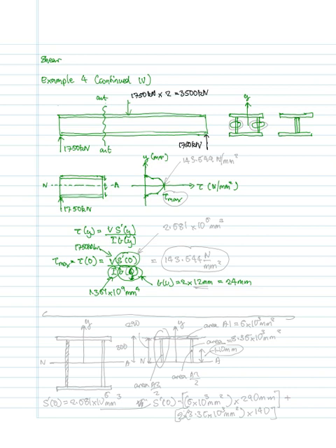V in this case here is going to be 1750 kilonewtons, and then I for the composite section we have already calculated as being 1.361 times 10 to the 9 millimeters to the 4th. So all we have left to do is to calculate this S dash of 0. So let's do that as an aside.